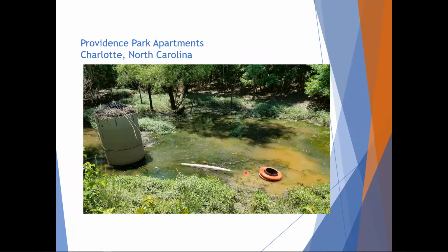So we've actually replaced that with a PVC pipe and just keep an eye on it. PVC is probably going to deteriorate over 4 or 5 years, but it's not all that difficult just to replace a stick of pipe if they have to. But you can see how much trash and debris is still in this pond, but even with all this stuff, the skimmer's working really well and not clogging.